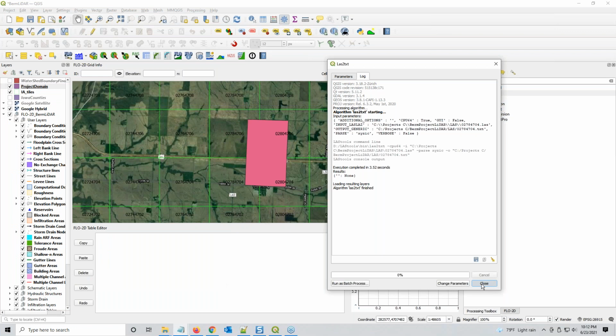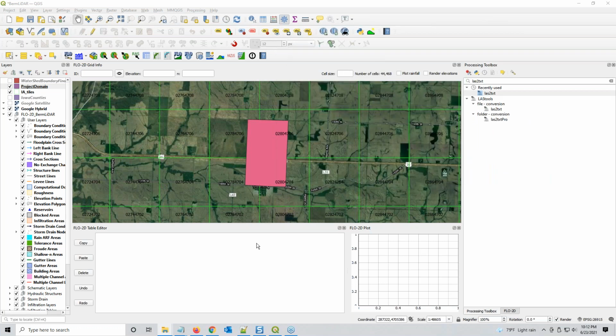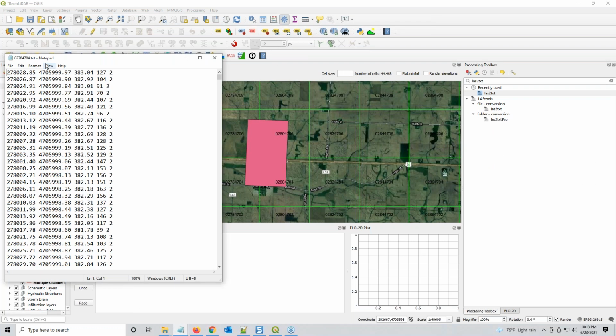All right, now, I opened this over here in the other window, txt. This is the file that we just created, and I'm going to open it here. And so you can see that it's space delimited data: X coordinate, Y coordinate, Z elevation. Now remember, this is UTM and this is meters. This is the intensity field that I was telling you about, the strength of the returning light signal, and I don't really know what the range of data is, so I'll just ignore anything about that.